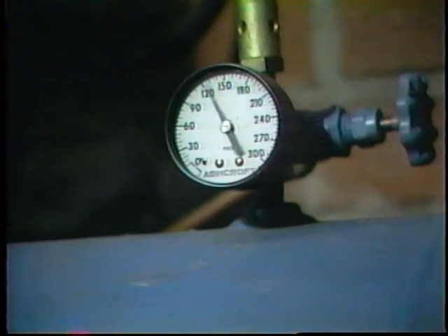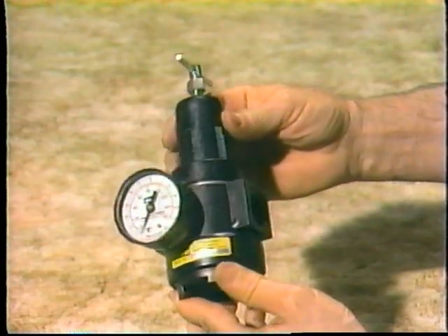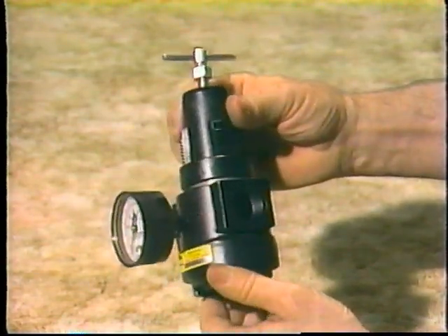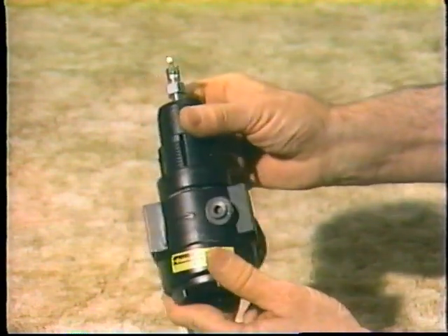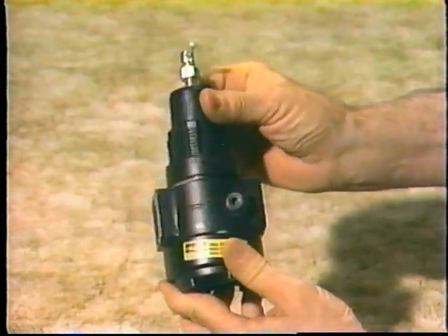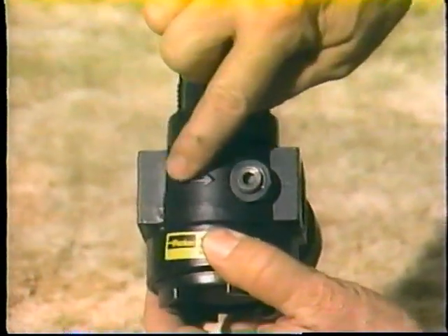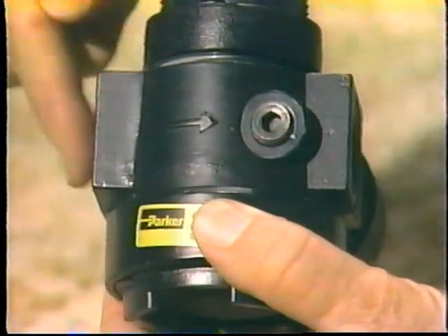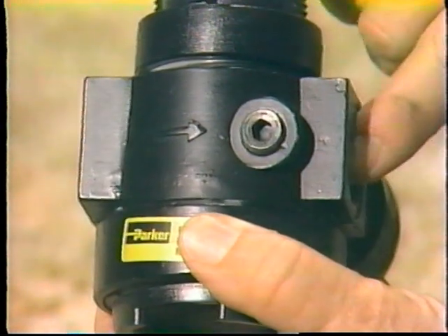Well, both pressure switches and safety relief valves are used primarily to control the pressure at the air receiver tank. But it's important also that we be able to control or regulate the air pressure that goes to the other parts of the circuit. Here is the device that we use. It's called a pressure regulator, and most regulators look pretty much the same, no matter who makes them. Here is the inlet port, and this is the outlet port.